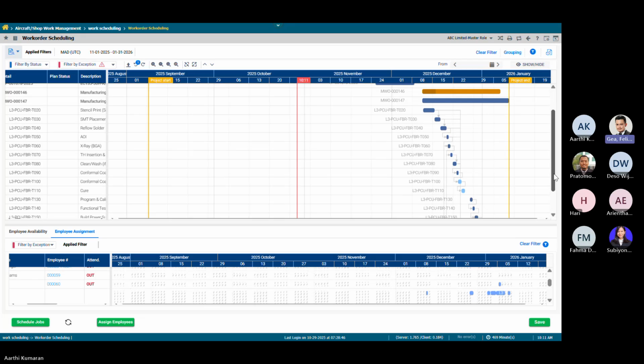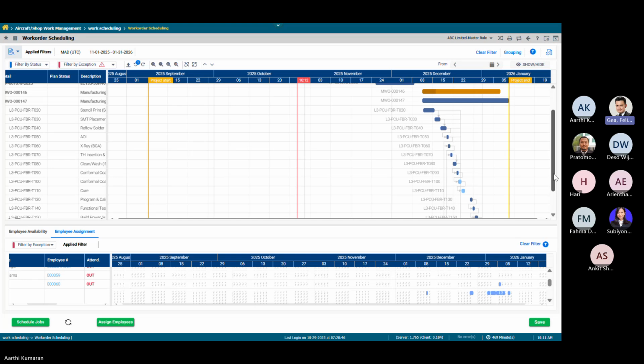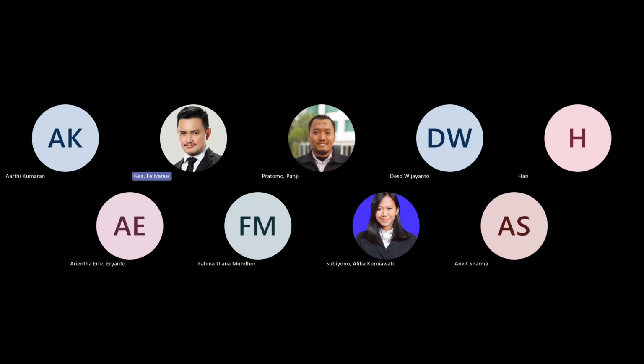So what we will do is this: for a chemical cleaning, the task is going to be the same, the cleaning task. You bulk different work orders, all going to the same task, and then you put 1%, and we prorate its time according to the number of work orders. There is some logic for that. So basically, let's say it's an 8 hour task, and you're doing it with one mechanic, and there are 4 work orders. Then approximately 4 hours each. Total time divided by the number of work orders.